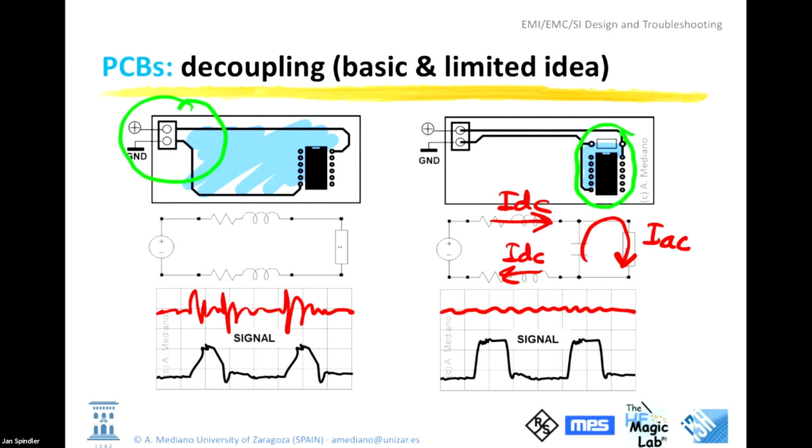You will not be able to filter. You will not be able to reconduct the energy to other areas because it's in a multi-layer PCB and it's very complex to control. So at the end, you will need to add filters in the cable, or you will need to seal the full product in some way.